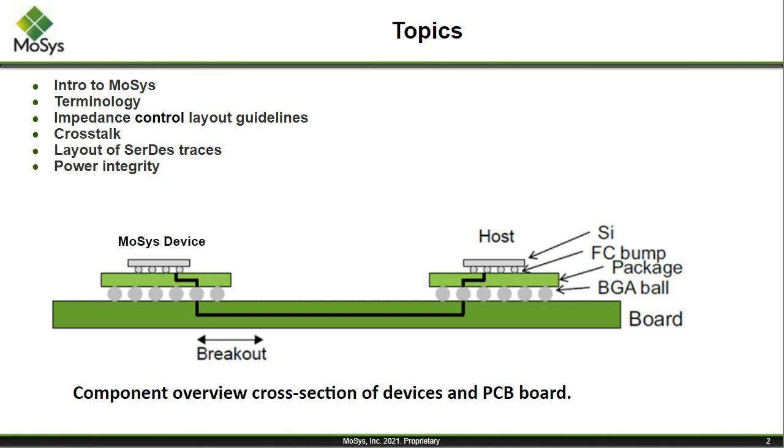Mark, I'm sorry to interrupt. One thing I forgot to mention in my introduction, MoSys also has a family of 100 gig PHY ICs. We talk about having a lot of SerDes expertise, and I was remiss. We have a family of gearboxes and retimers similar to the products that you might be familiar with from Broadcom and Marvell. So I want to throw that out there as well. So there's two IC families, the high-speed memory with the serial interface, and then 100 gig PHYs based on 25 gig NRZ SerDes, and then, of course, the packet classification IP. Back to Mark.